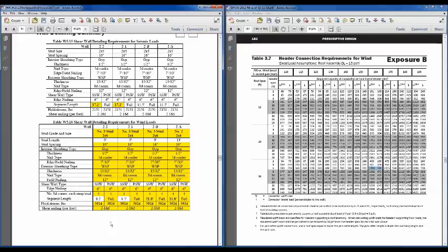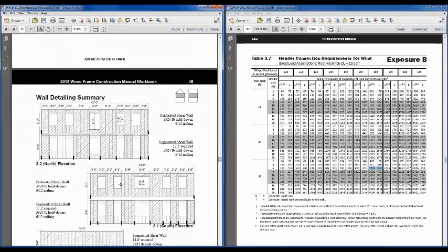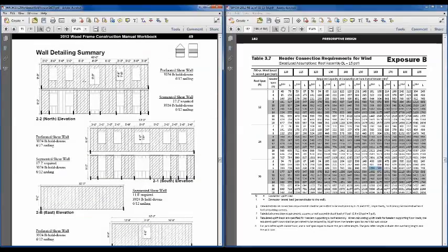So it's a pretty interesting comparison there again between seismic and wind. I hope you're seeing, especially out in seismic country, and I know this is a very high wind load, but if you've got wind loads that approach anywhere in your area 160, that can very easily start to control in the design process, because we're designing for a D1 here, and that's a fairly substantial seismic analysis as well. And so you can see those comparisons here. We looked on page 49 earlier at those differences.